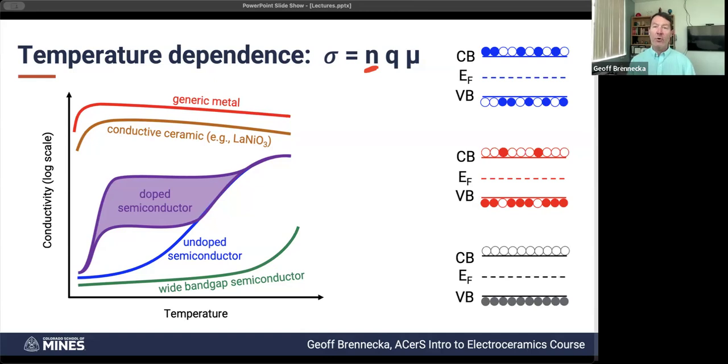When we start talking about more complex materials, so we'll get to doping PZT later on as one example, we can have multiple different compensation mechanisms. So we might not just add an electron for every donor dopant that we contribute. It might be compensated in other ways. So to first approximation, yeah, every donor you throw in, you get a free electron. But there are always different mechanisms possible. So that really only applies for pure semiconductors.